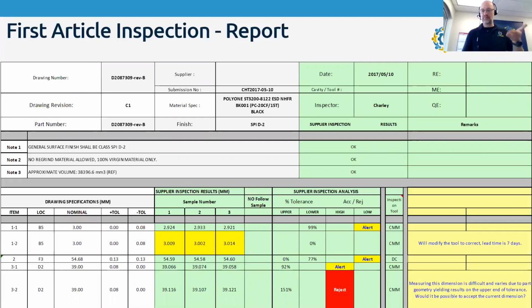If you require 100% on all the dimensions that you lay out, we certainly can do that. Sometimes it requires a little bit more than what we've budgeted in, so we'd have to have just some nominal fee added, but we can do it. Also, it depends on the quantity of parts that you're running. Sometimes if you're running thousands of parts, doing 100% inspection just isn't really feasible. So there's often a quality plan, a CPK kind of thing, where we may choose a few, do some statistical analysis on it, and see from the results that it's good enough that all the rest of the dimensions on the part should be acceptable.